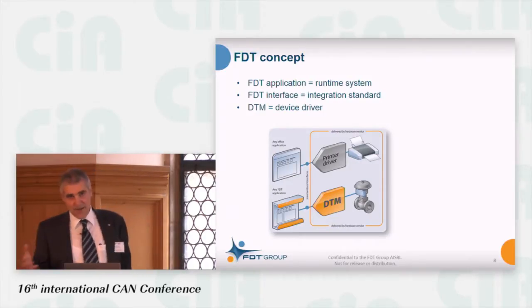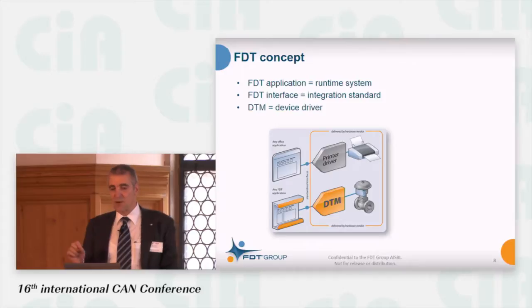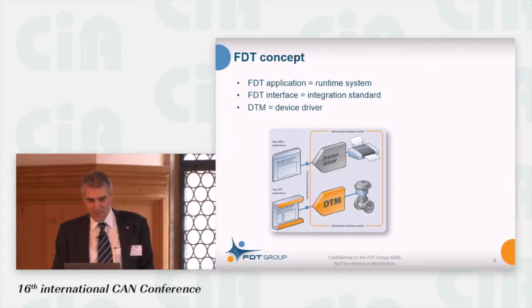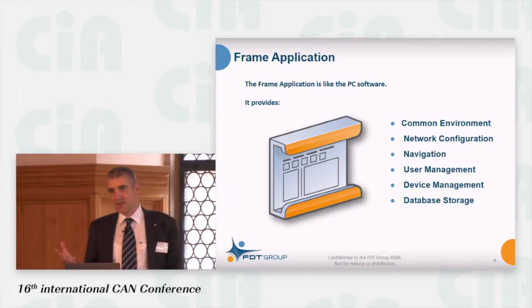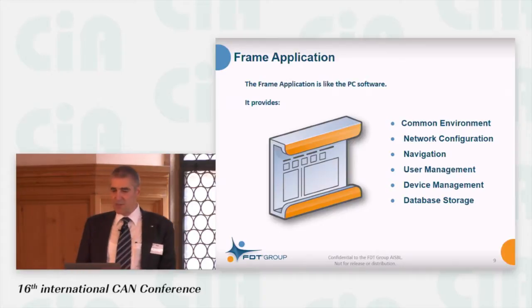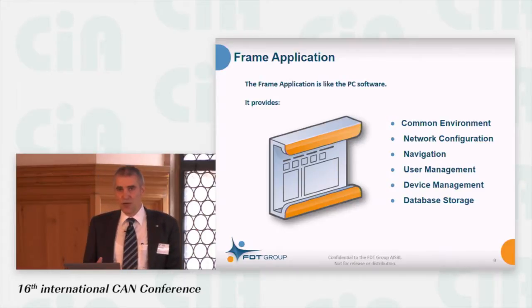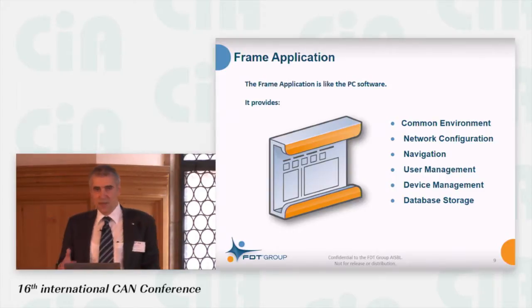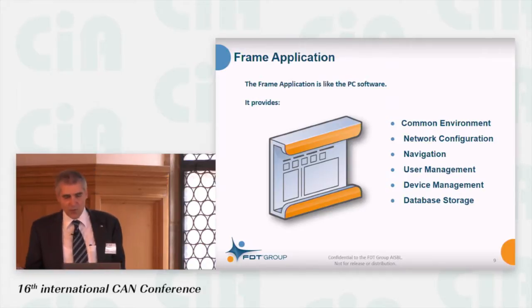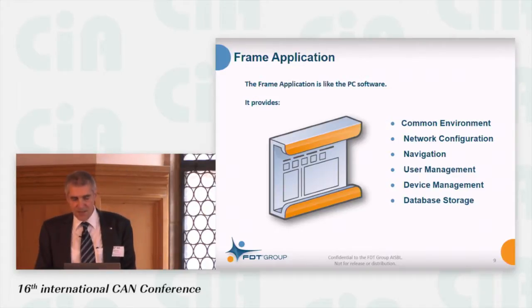So each vendor or manufacturer of such a field device provides a DTM, which is a device type manager. And the frame application is able to let these DTMs run in its environment, so it provides a common environment for the DTMs. You can configure a network depending on the application you use. It provides navigation through your application tree. You have user management, device management, and of course a database storage for all these devices in the same manner.